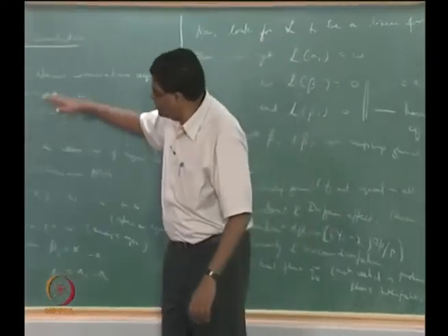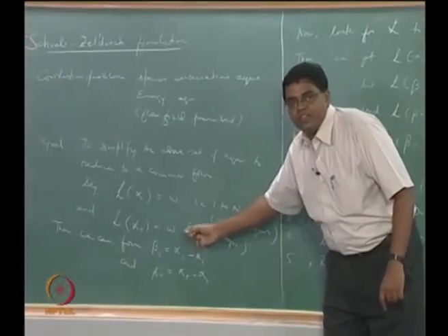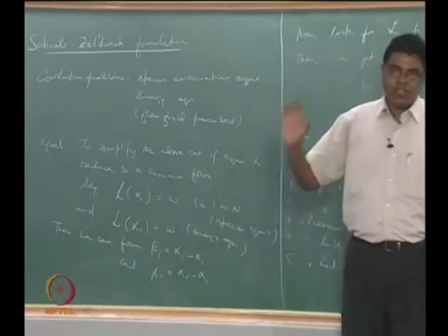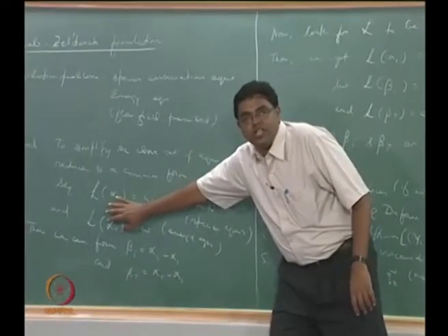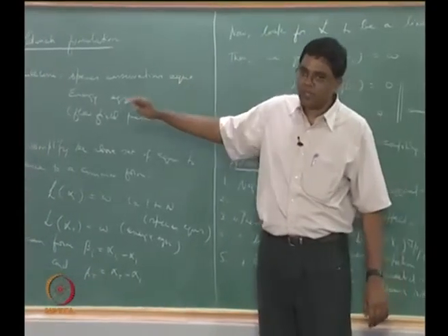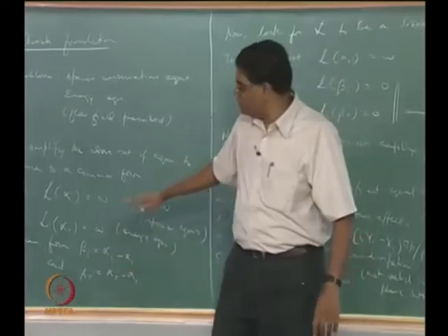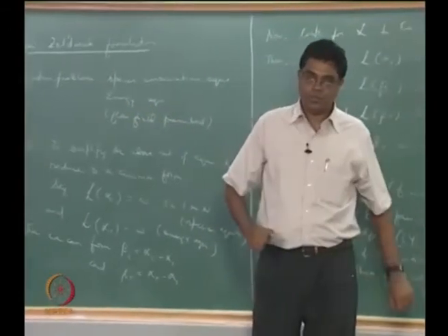Because these equations are essentially, remember, convection, diffusion, reaction. These are the three things, and if you had some sort of intuition, you would say that omega stands for reaction, not just because it is the symbol, but because I have been saying that this is the one containing the nonlinearity in the Arrhenius term, which is essentially from the reaction. So if you say convection, diffusion and reaction, and this contains the reaction, then this is going to contain the convection and the diffusion. Sure enough, prescribing a velocity, you simply have a non-constant coefficient for the convective term coming from the flow field, and the diffusion term should be linear just as well as the convection term. So we expect this to turn out to be linear. That means we are looking for two terms here, both of them linear, one coming from convection, the other coming from diffusion.